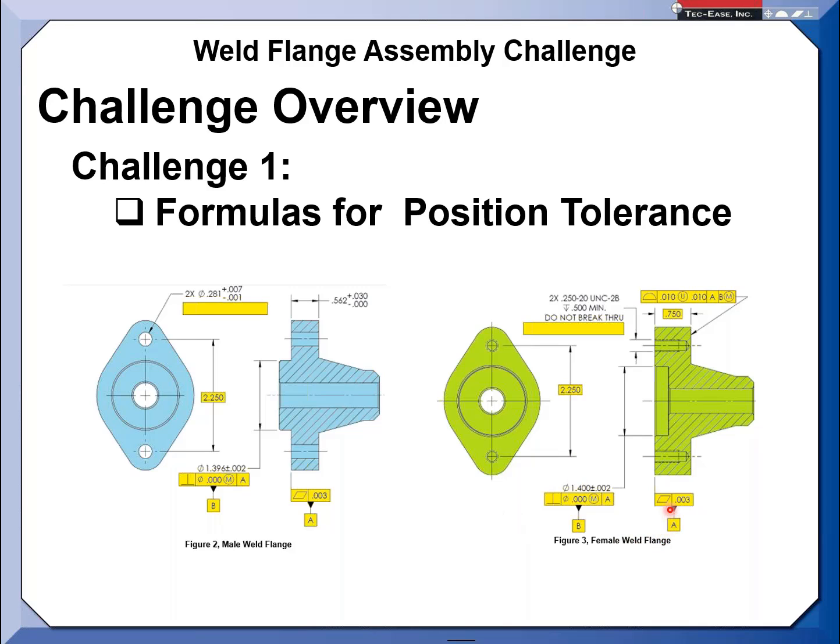Now there's a lot of other things involved. I kept it simplistic, you know, how the datum features act. I didn't bring in datum shift, but that's another element that may be involved. But I will say this: notice that the holes are always basic. The tolerance zones we're talking about are locked in those basics. Datum shift is not additional tolerance. In this case, dealing with these features, the shift itself, datum shift, and the mating relationship between the bolts and the holes are based on the positional tolerance. And that's definitely way beyond the scope I want to talk to for these challenges.